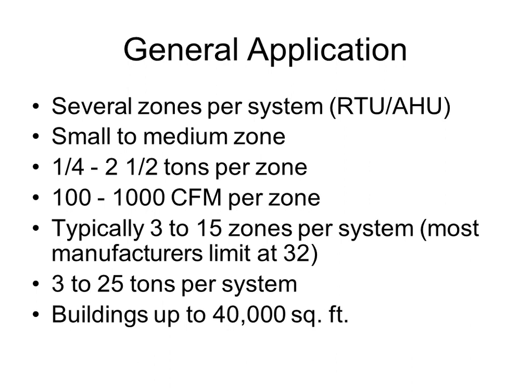Typically, you don't really want to go over 15 zones. I mean, under 3 zones is maybe you just have one rooftop unit. You probably don't need zoning. But for over 15 zones, generally speaking, you have a requirement for cooling all the time because it is a big enough building for that.